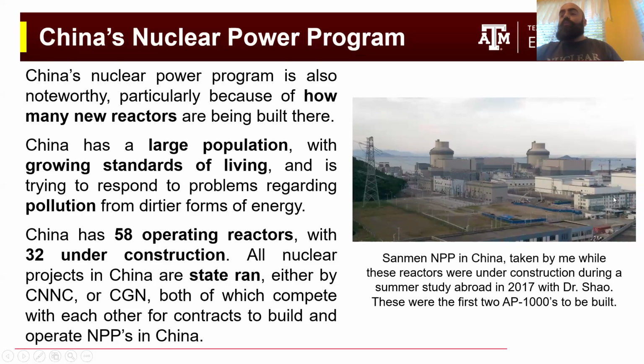So if they were to lose on-site power, then these pools above the reactor would open up some valves that would allow that coolant to flow downward, and that coolant would flow eventually over the nuclear reactor core and would allow for maintaining the temperature of that reactor core.